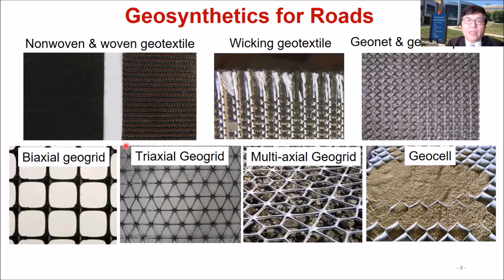All those products are basically called primarily geosynthetics. The last product is geocell. This geocell has height, and is basically a 3-dimensional honeycomb-shaped geosynthetic product. All the material, if infilled in the pockets, will be confined.